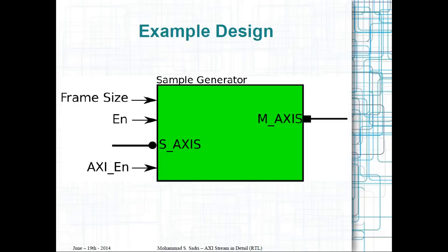So initial synthesis is generally a very good idea whenever you design something. Before going to functional simulation, even a quick initial synthesis may indicate some important points to you, and after you did that, you go to functional simulation. So we also create a sample test bench, and we test the operation of this unit, and we will look at whether it is working or not.